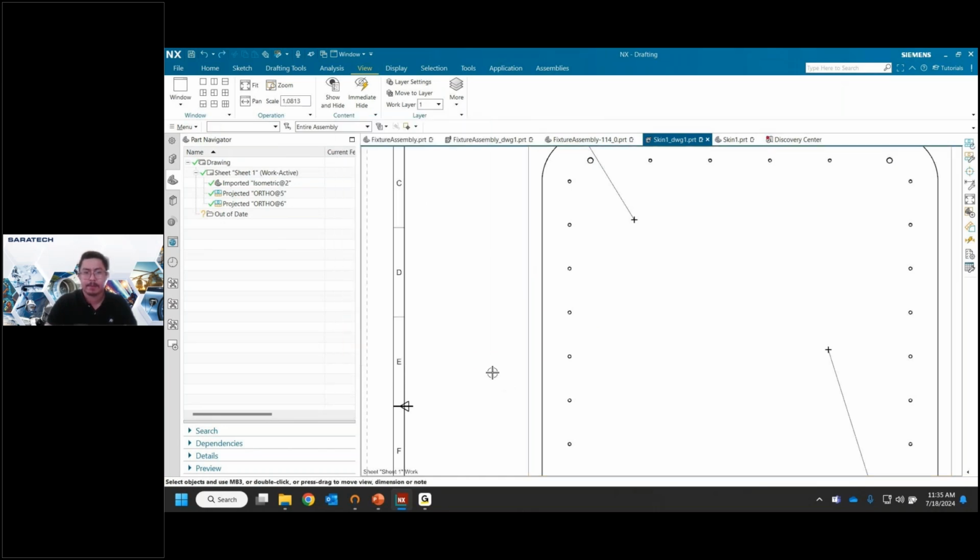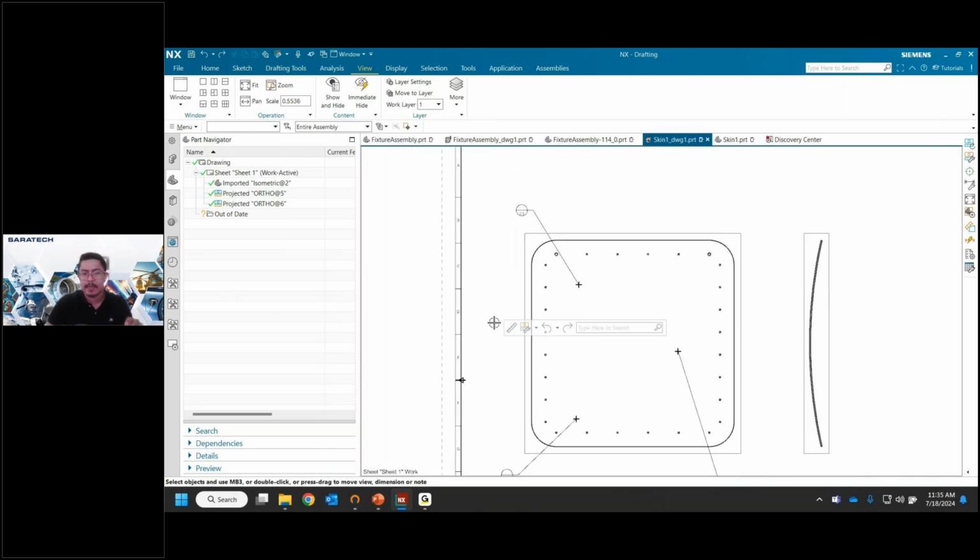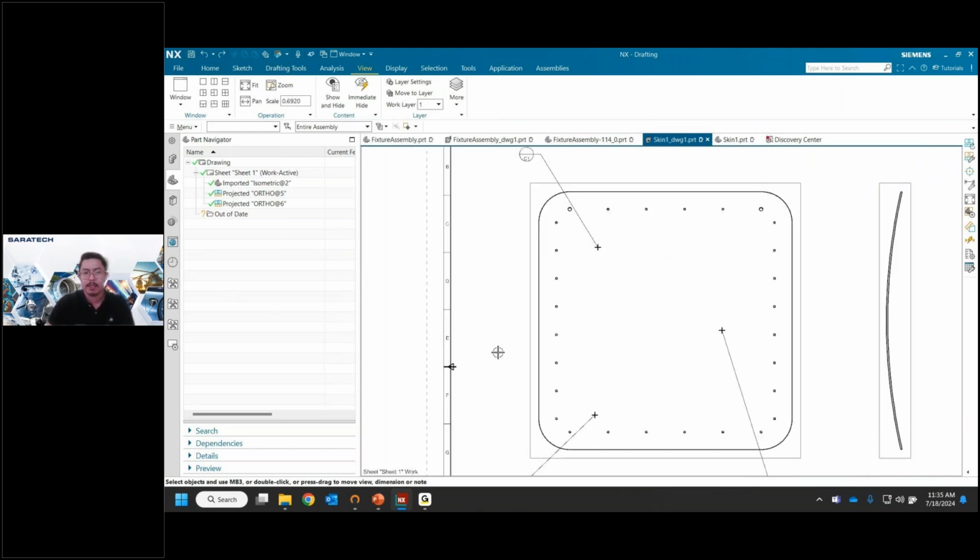The good thing is the Checkmate test has a test for any objects that were altered using view dependent edit. So if you want to make sure no one's accidentally modifying the drawing of the component, you can do that check to validate that. So yeah, two different options there.